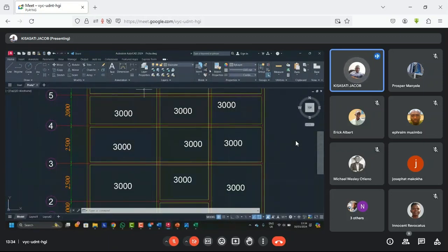You can perform the design and everything of the structure and do the design of the staircase later, because if the contractor is not going to construct the staircase at the stage where the building is being constructed, you can perform analysis and design later. I think that one is noted. You have monolithic and non-monolithic. Monolithic, you have to perform this design together as you perform the design of the other elements. Non-monolithic, you can just leave the staircase and do it later because it will be needed later for construction. So for this one, we'll assume non-monolithic.